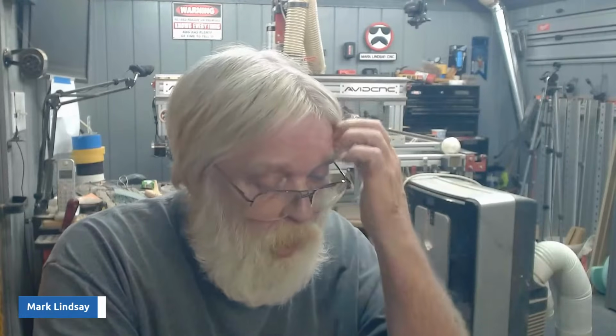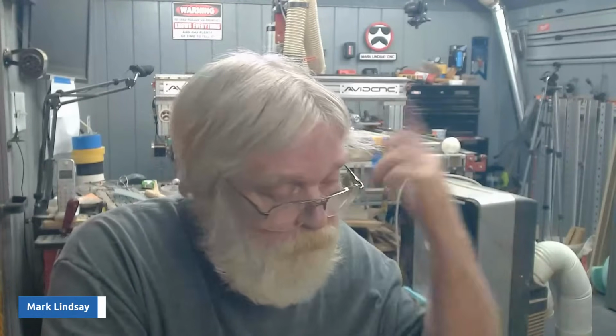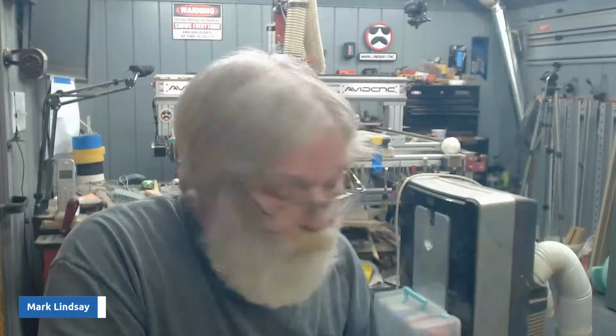Then you have to figure out, did you lose a power supply? Is it a connection on the power supply? Is it the breakout board? Is it a connection on the breakout board? Is it a separate controller for each motor? Is there a separate power supply? What's going on? So, again, divide and conquer, eliminate the variables.